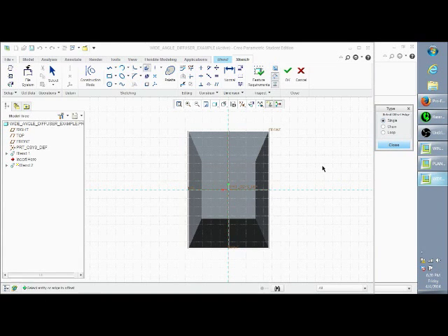And to get a clean offset in without having to erase some features, you can select this loop tool, select this whole green surface that's highlighted right now, and then notice that the arrow is actually pointing in the direction that we want, and that all 4 surfaces of your square are highlighted. You want to make sure whenever you use this tool that actually happens, and that those are all the surfaces that you want. So now we have this, we can go in and offset it by 3/4 or 0.75, and you can hit enter, and there you go.